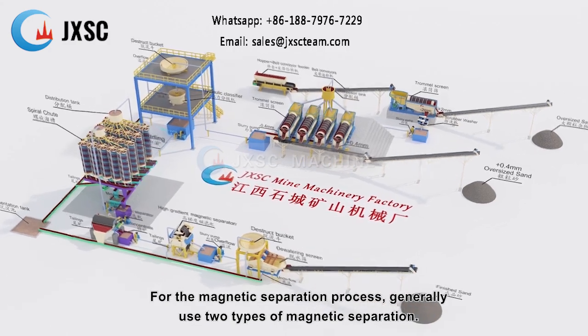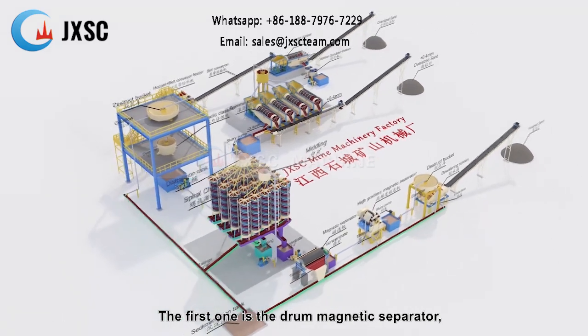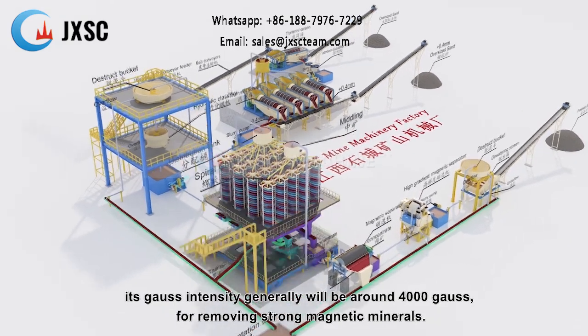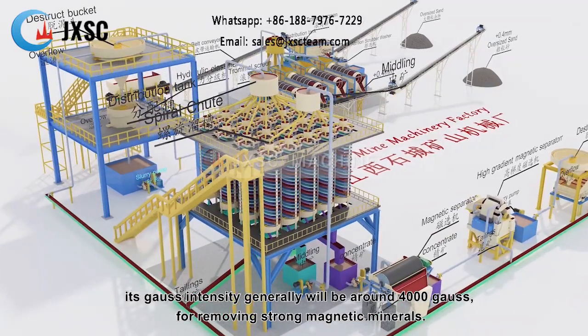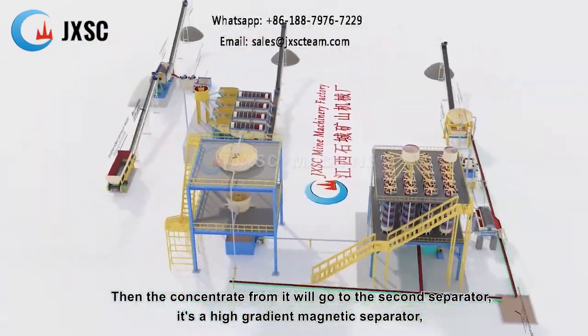For the magnetic separation process, generally use 2 types of magnetic separation. The first one is the drum magnetic separator. Its Gauss intensity generally will be around 4,000 Gauss for removing strong magnetic minerals. Then the concentrate from it will go to the second separator.